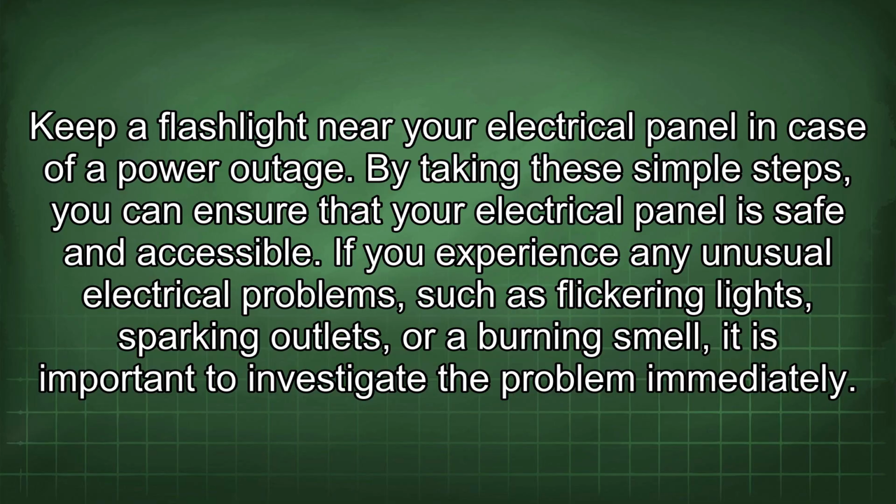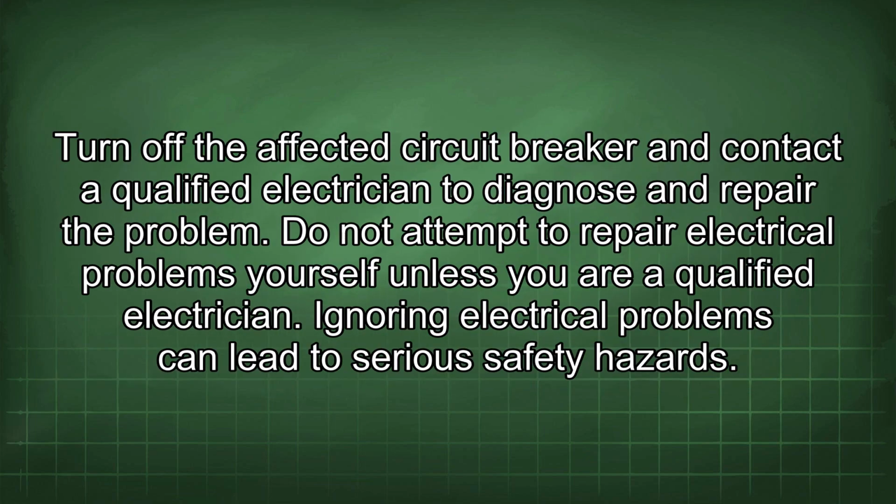If you experience any unusual electrical problems, such as flickering lights, sparking outlets, or a burning smell, it is important to investigate the problem immediately. Turn off the affected circuit breaker and contact a qualified electrician to diagnose and repair the problem. Do not attempt to repair electrical problems yourself unless you are a qualified electrician. Ignoring electrical problems can lead to serious safety hazards.